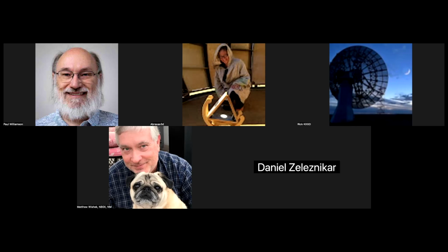We also have done some work on a link budget for an Earth, Venus, Earth project that we learned about from the Deep Space Exploration Society. For the first draft of the modified link budget, we took Jan King's DVB-S2 GEO HEO link budget for 10 and 24 gig, and we're using that as a base, and we're going to modify that link budget for Earth, Venus, Earth.